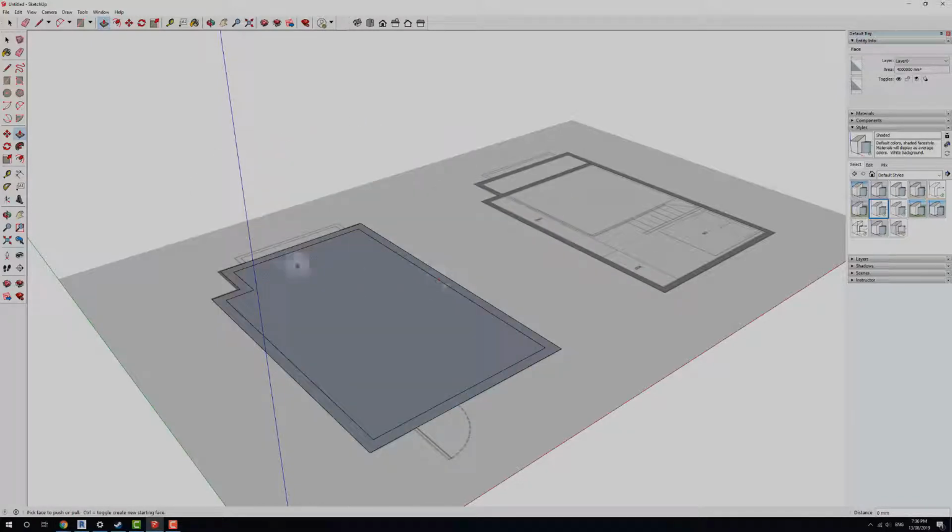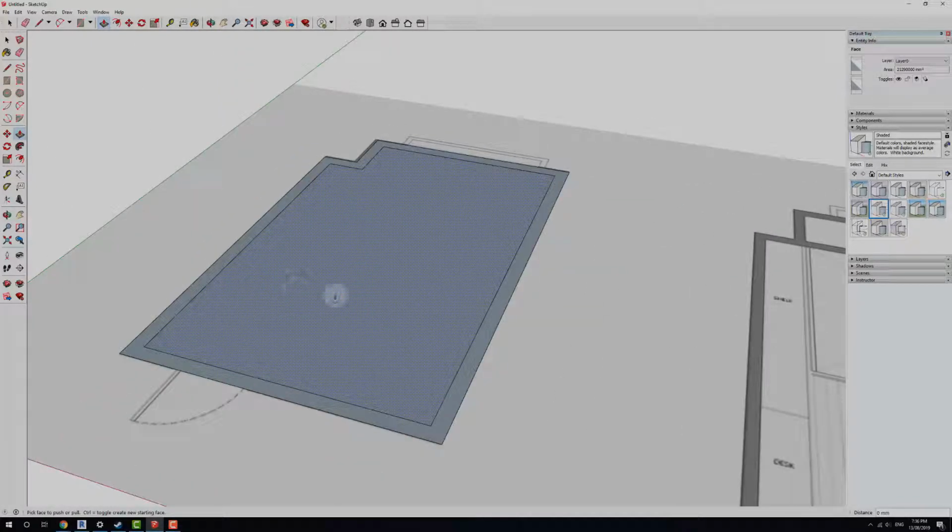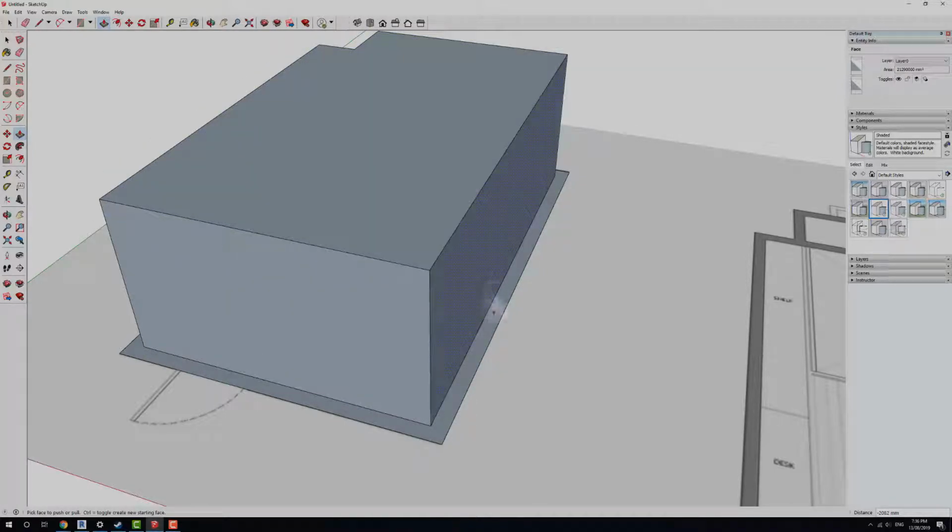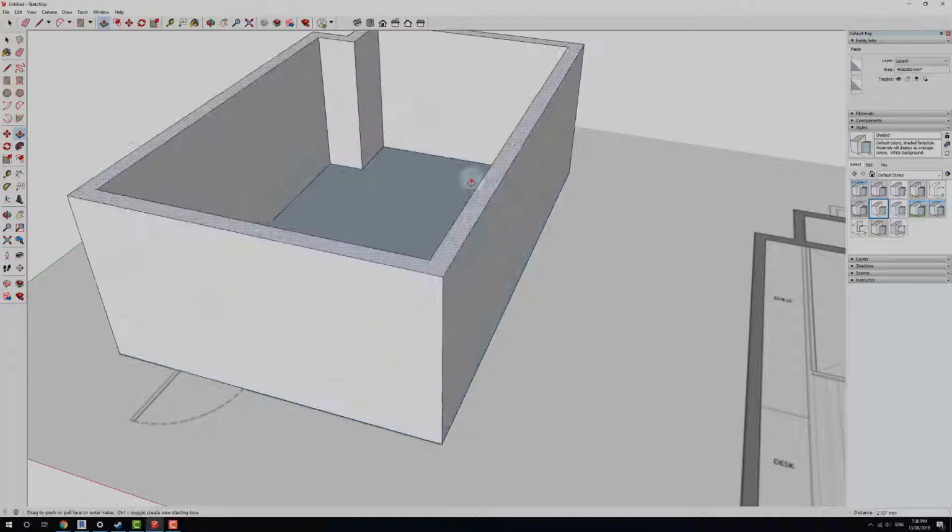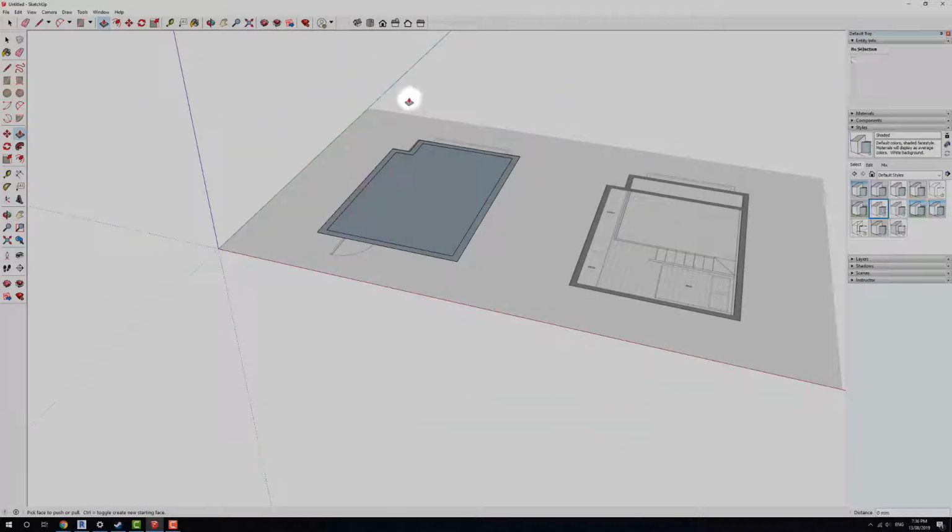This is also very, very important, because if you have a look, we've now got a blue shape coming out, a bluey gray, and we've also got a white shape. Now, in 3D modeling, you've got a thing called normals. Normals are the things that are at the front or outside of a shape, and the inside of a shape. Typically what you want is all your normals facing the correct way, which means white should be on the exterior and the bluey grey should be on the interior.